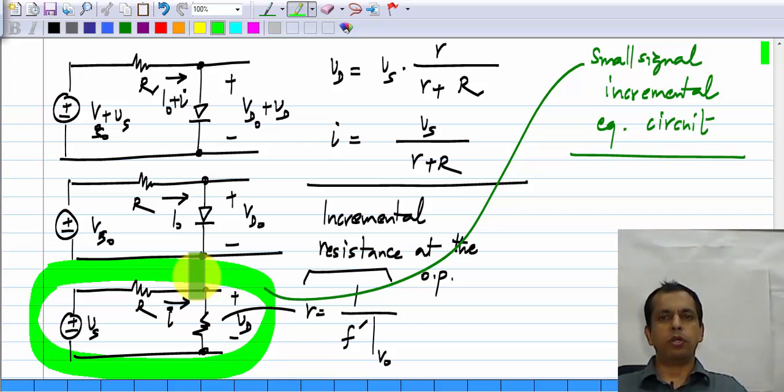Okay. Now, what is sufficiently small is very dependent on the nonlinear element you have, and so on. The only definition I can give is that it should be small enough, so that second order and higher order terms should be negligible. And also, when you say negligible, you have to specify some accuracy. So, depending on the accuracy of the solution you want, you can restrict the size of the increment.